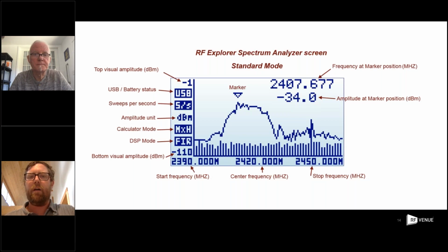So looking at an output on, say, a distro, so that you're seeing exactly what the receivers are seeing, you get a better understanding across the operating band, not just within the range of the particular receiver that you have on hand. Things that are out of band that you're not seeing that could be contributing noise within your range of interest. That's really where spectrum analysis comes in key, and where you can get a lot smarter about how you configure these systems.